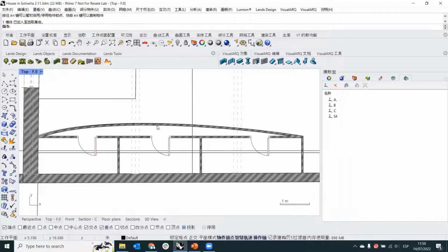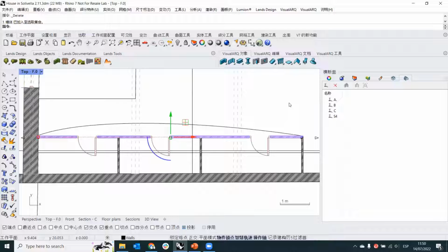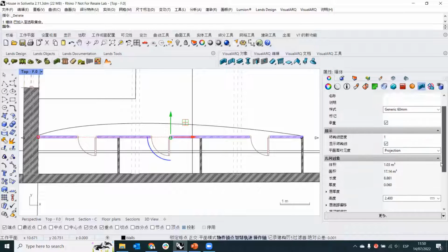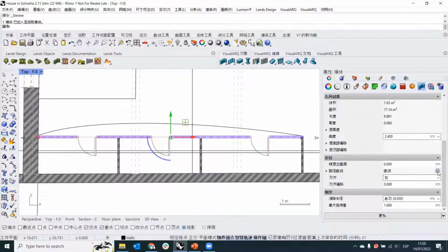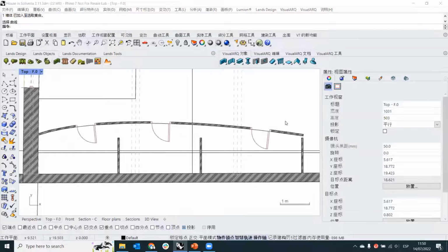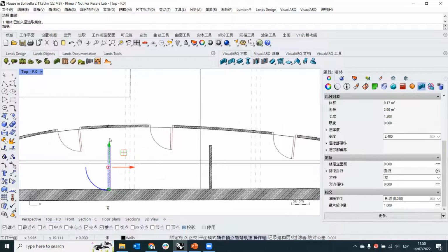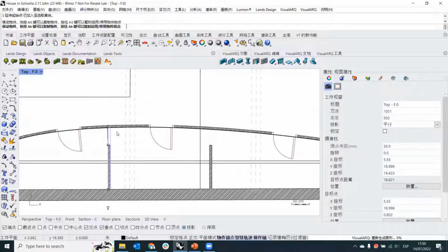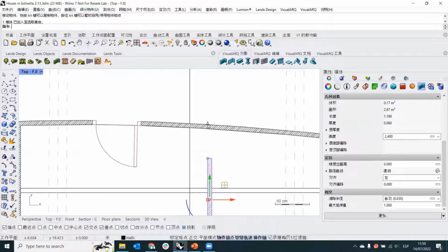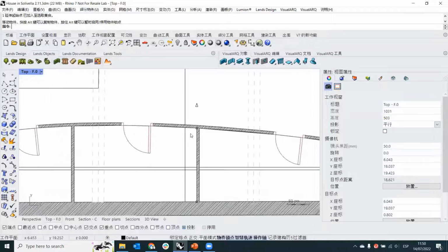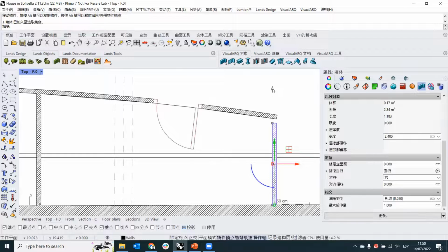Another option we can do is to change an existing wall, and we can edit its features from this panel, and we can also change the path. So we click on this icon, and now we select that curve. In that case, all the doors will keep attached to the wall and will snap into them. Of course, these walls are not following, so we can just extend them using these extension arrows. So we can extend them until they hit the wall.